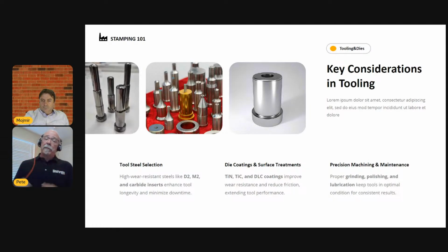Or we may even just take the lubricant and just spray that corner, and you get all kinds of lubricant in there. Remember when we were talking about deep drawing, how I explained that the flange thickens and that thickened material ends up going into the walls? Well, if you look at the four corners of a deep drawn box, if you would put those together, what do you have? A cylinder, a cylindrical part with a square flange on it. So those corners are going to behave like cup draws. The walls are going to get thicker. That's why they look so shiny. You're actually ironing the material.